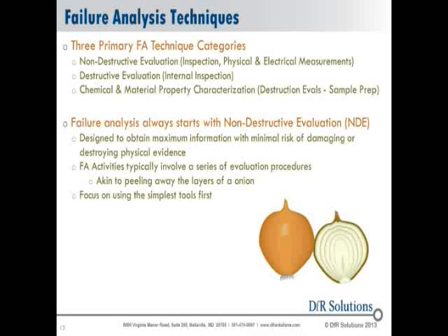till we have learned as much as we can from various non-destructive evaluations. And then there's another category of what's called material and/or chemical and material property characterizations. Now, usually these are destructive evaluations because you have to form some kind of sample out of the device in order to put it into a specific series of tests to see if the device stands up to expected material properties or electrical performance parameters. So these are the three general classifications that may come to bear in a particular type of failure analysis project, dependent upon what you're analyzing.